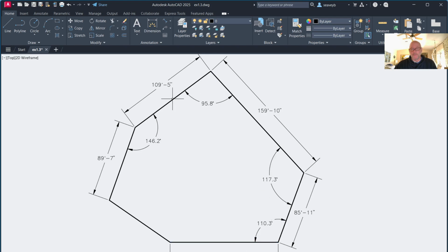as to start, and that'll set your frame of reference basically for the size that you're going to be making. So I'll type in limits. If you don't do this, what ends up happening is your first line, like if we start at the bottom here, it'll be 125 feet and 5 inches. The line will go off the paper because it'll be zoomed into your limits, and that'll be like a 12 by 9 piece of paper. So then you won't be able to like zoom while you're drawing and stuff. So this sets your frame of reference, and then you can zoom to those limits, and then you're good to